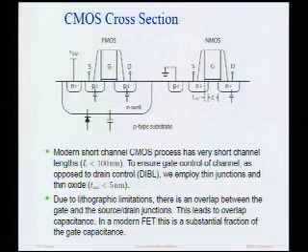The shorter we make the channel length, the better. And probably the advances in integrated circuit technology for the past 20, 30 years have all been about making that channel length shorter and shorter through lithographic technology. In fact, today you can go out there and buy a transistor with 90 nanometer channel length. Actually, the effective channel length is even shorter, about 60 nanometers. So we're talking really big tiny channels here.